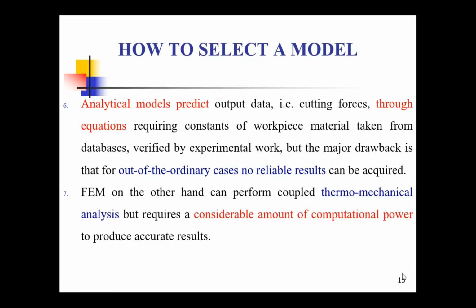Nowadays, FEM models are coupled with thermomechanical analysis, that is thermal as well as mechanical. So the cutting pressure, the cutting temperature, the stresses, cutting forces, and the tool wear, everything is coupled with the finite element models.